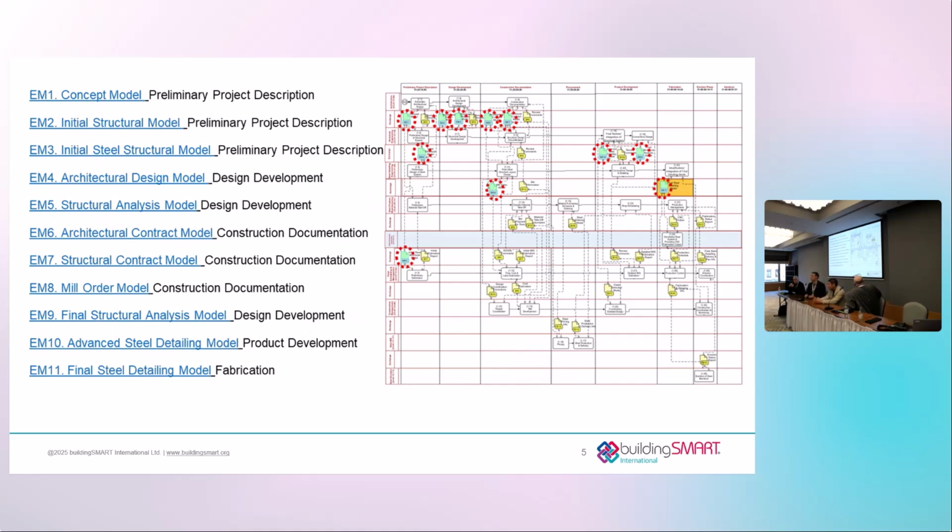To send a model directly to fabrication, you might use CIS2 files, IFC files, CNC or NC1 files, KISS. They were used, proprietary file formats for all the different machinery that existed. And all of these take effort to manage. So you're not just able to simply send the file quite as easily as you might like and have automated steel fabrication. While we have a labor crunch and automation sounds great, it kind of opens up an additional bottleneck.